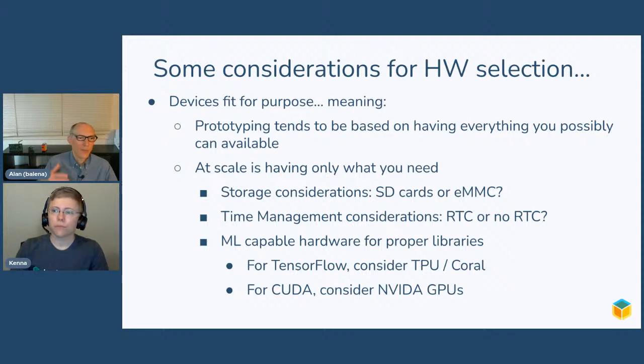And we can mention that balenaOS is optimized in many ways for the edge. So it is optimized for SD card writes, to not hammer the SD card if possible, but that's application dependent. There are just sometimes where the OS is not going to be able to help. If, for instance, you're running a massive database on an SD card, then there's only so much the OS can do to minimize that extra writing. And logs. If you need to troubleshoot something pretty in depth, and you start generating more logs to understand the problem, you're going to generate more wear on the SD card, and that's just a fact of life.